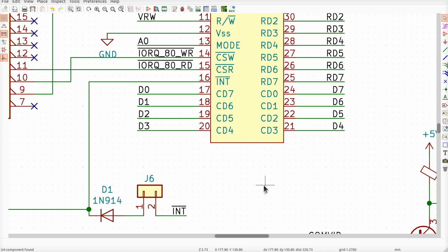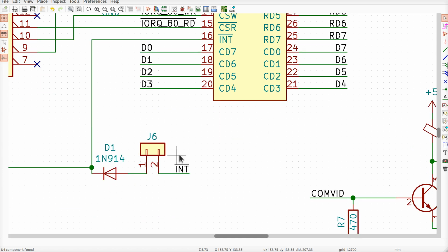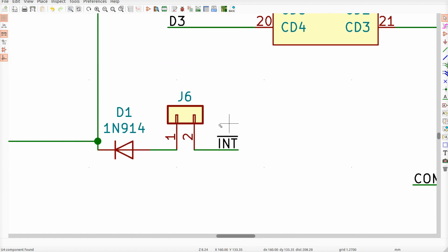if you really do want to generate interrupts from the VDP and you want to be running in mode 2 because maybe you also have interrupts going on with the SIO and or the CTC. And that technique is actually used on the, what was that? I believe there was a Z80 home system that did exactly that with the TI-99 VDP. Oh, what was the name of that piece? I'm embarrassed. Well, that's what the comments are for below on YouTube. Remind me which machine did exactly that, will ya?